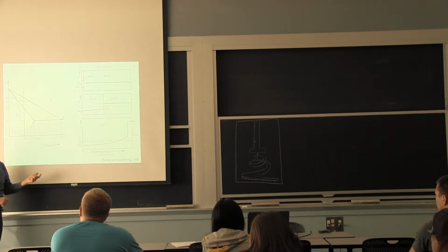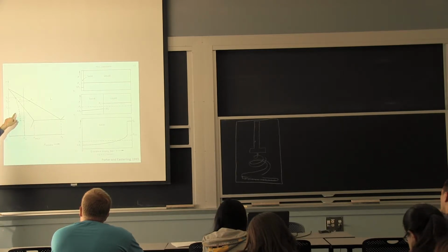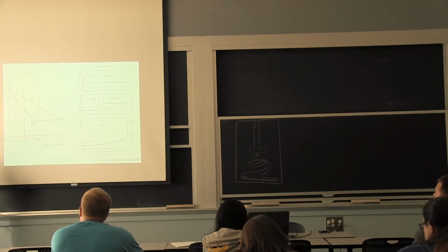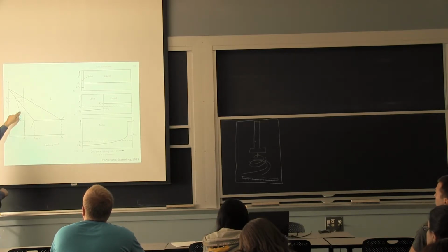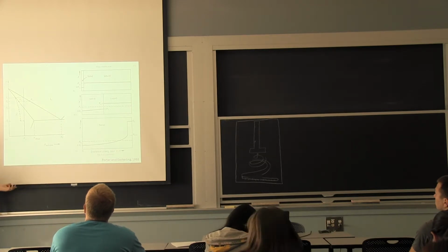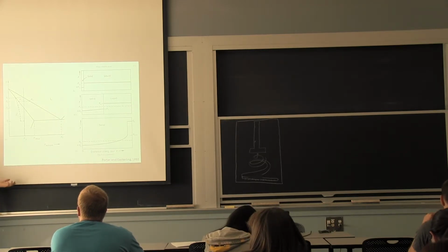But there are a lot of conditions where these alloying elements are very helpful in terms of improving mechanical properties. That's the reason why we use them. In all the aluminum alloys, we take advantage of the reduced solubility to form precipitates that increase the strength. So what is the disadvantage in terms of making the alloy is the main advantage after the fact when you're trying to improve the properties. So we have to do it.